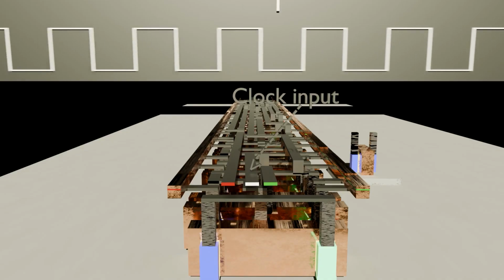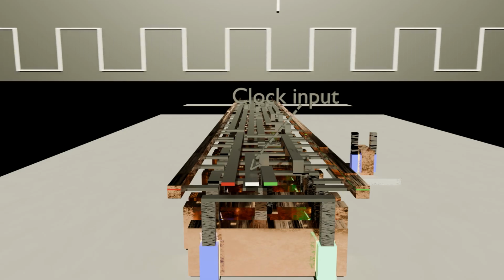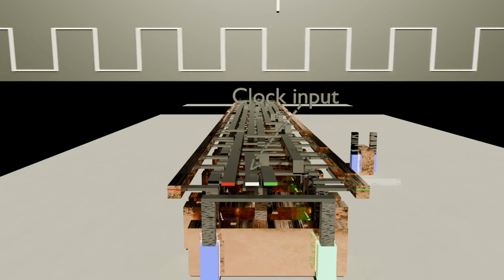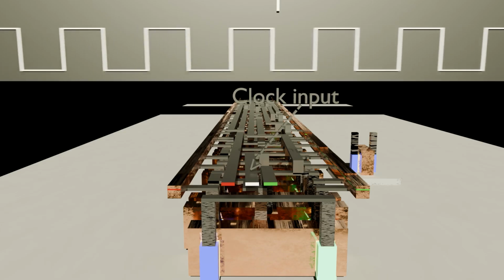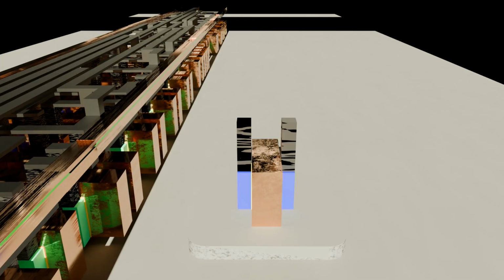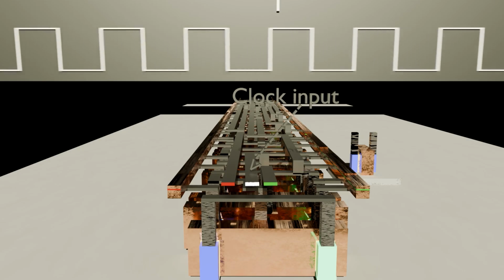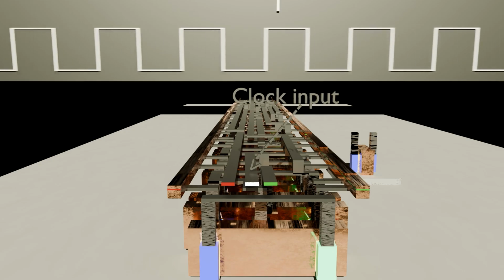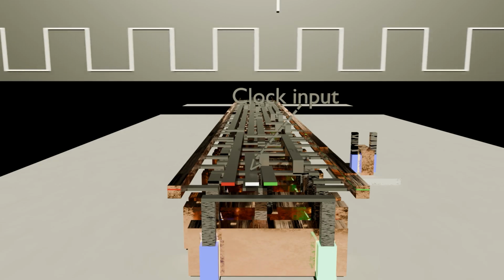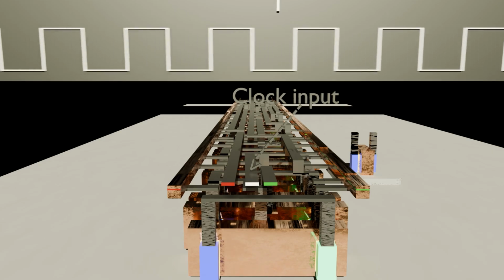This square-waved clock drives all different types of components throughout the computer, like for example, memory, as this D flip-flop here. And this leads us to combinational versus sequential logic. Combinational logic is just input to output logic. Sequential is dependent on its stored state. Like this D flip-flop here, memory is just logic that feeds back into itself. This flip-flop stores 1 bit and keeps on updating it each clock cycle.